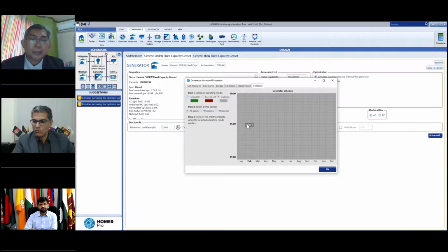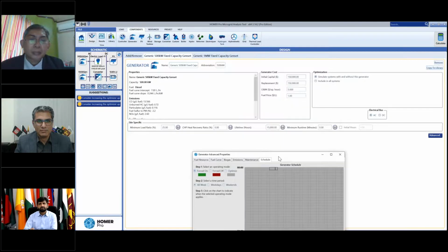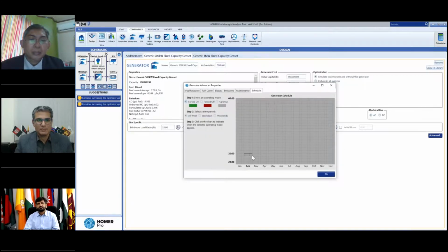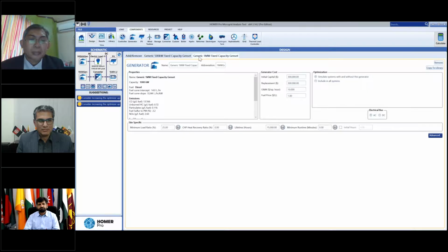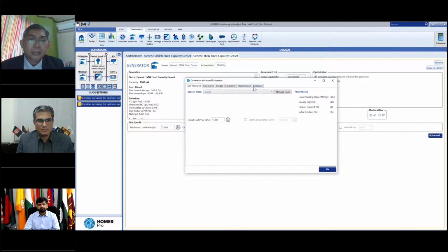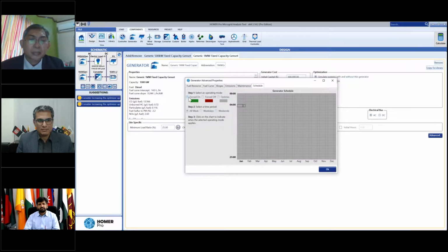I'm glad you brought that up. And that's different than what I was talking about. Here, you can simply force the generator on. So you click here, forced on, and you say, okay, which generator am I on here? I'm on the 500 kilowatt generator. So you say, we want this 500 kilowatt generator to run all night until 7 in the morning. And then maybe at 11 o'clock at night, we can force it on. And then we could go to the large generator and say, here under schedule, we're going to force that on during the other hours. The peak hours. Yes.